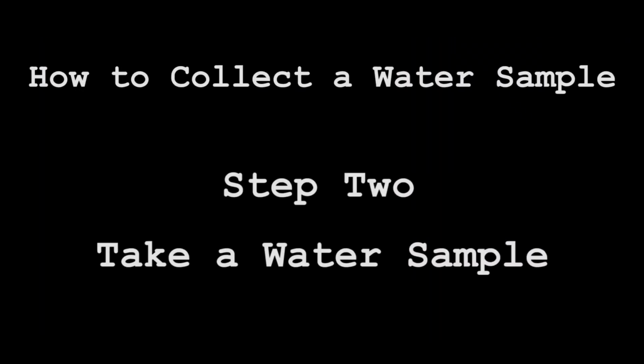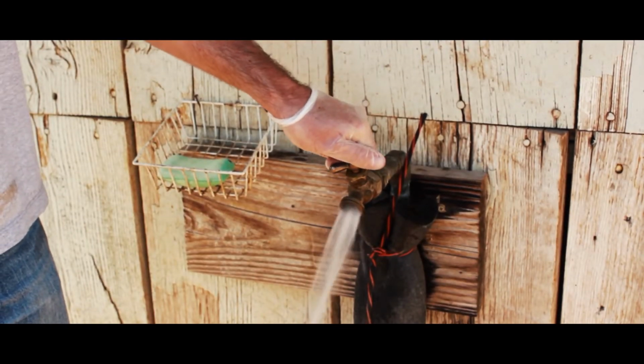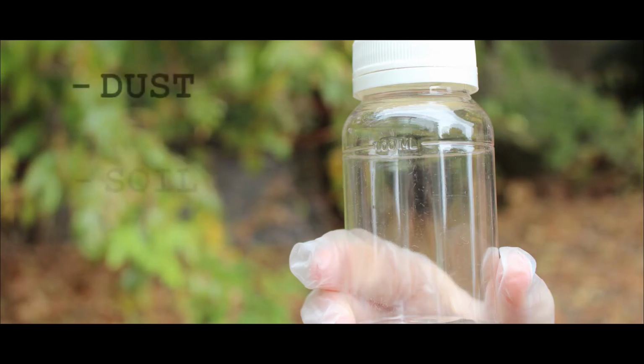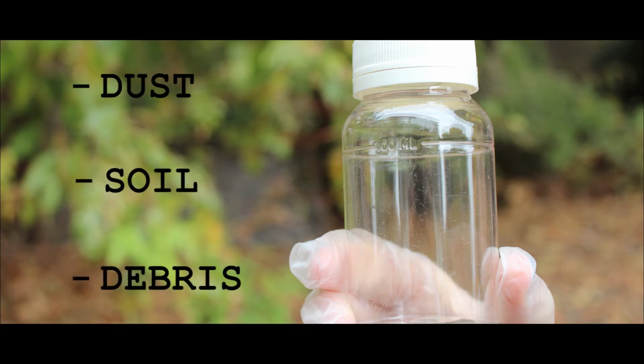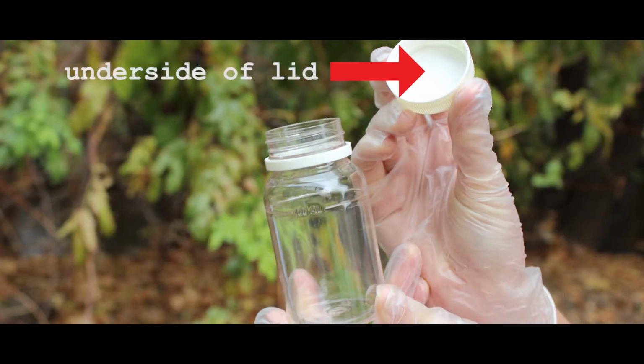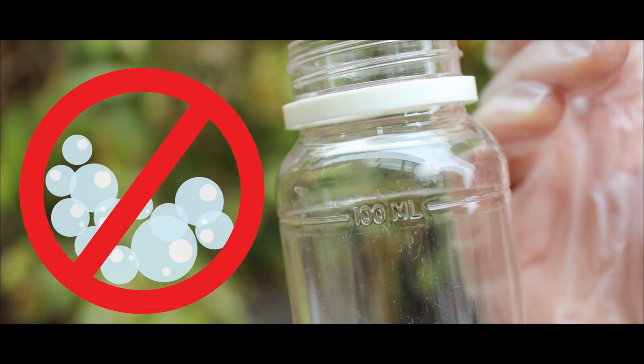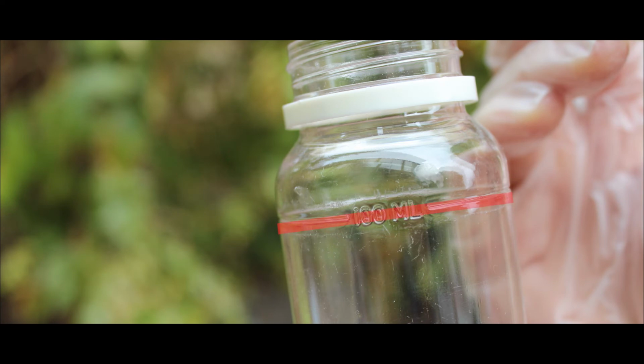How to collect a water sample. Step 2. Take a water sample. Turn the water to a moderate, steady flow. In order to prevent dust, soil, or other debris from contacting the sample container, keep the container closed until the sample is ready to collect. Do not touch the underside of the bottle lid, the bottle lip, or the inside of the bottle at any time. Do not rinse the bottle before filling and look for the fill line or 100 milliliter mark.